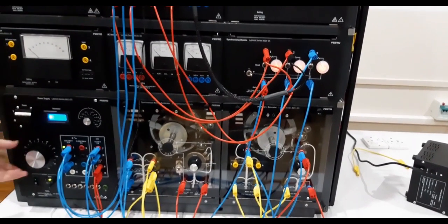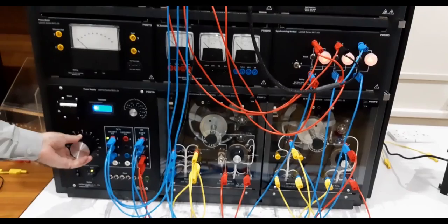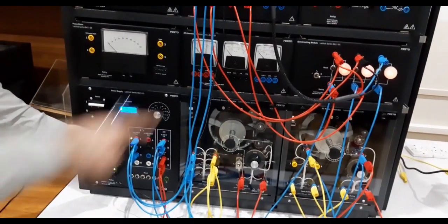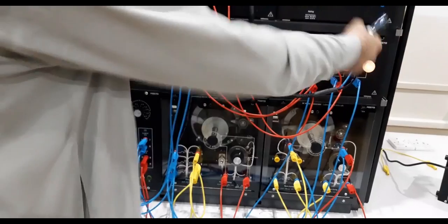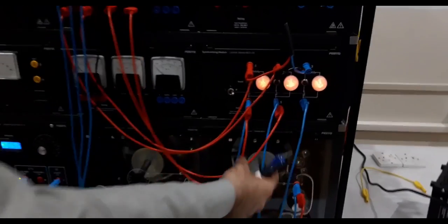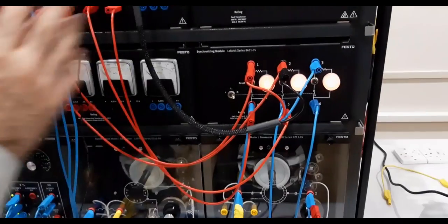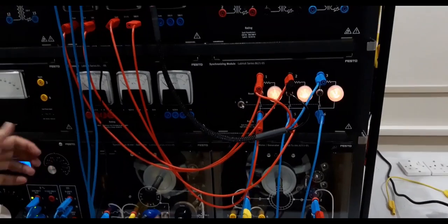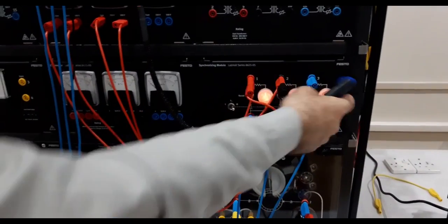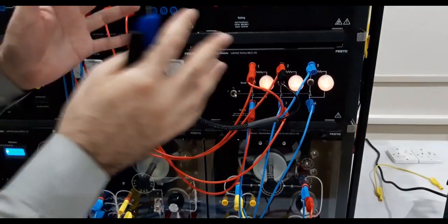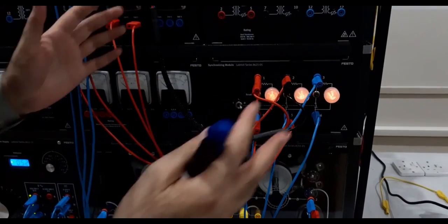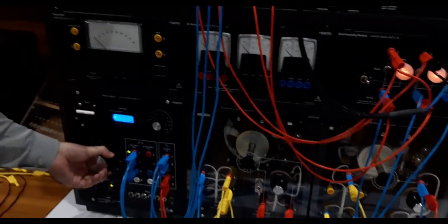Okay, first turn it on, and then you will see that by increasing the voltage, the speed increases. Also you can see the blinking of the lamps. We discussed it before. This is WAPDA, this is from the synchronous generator. So as long as we have blinking, it means that the voltage of the synchronous generator is not equal to that of the system voltage. So we have to make it a condition where there is no blinking anymore. So let me increase the voltage.